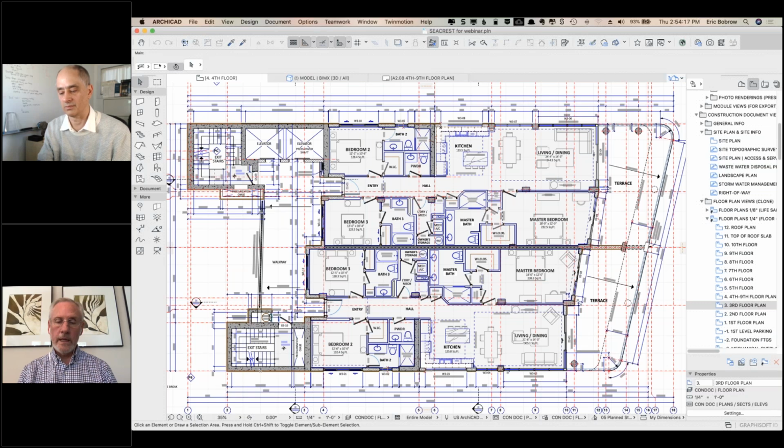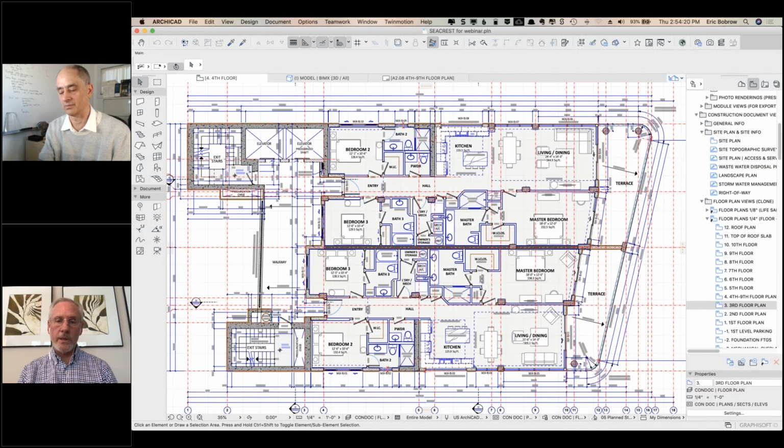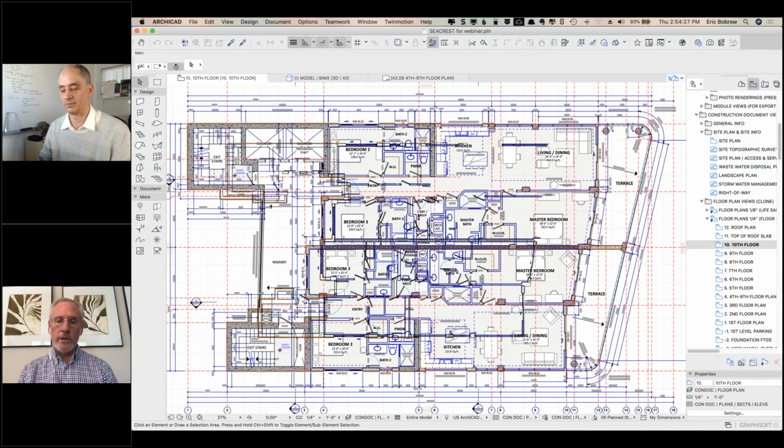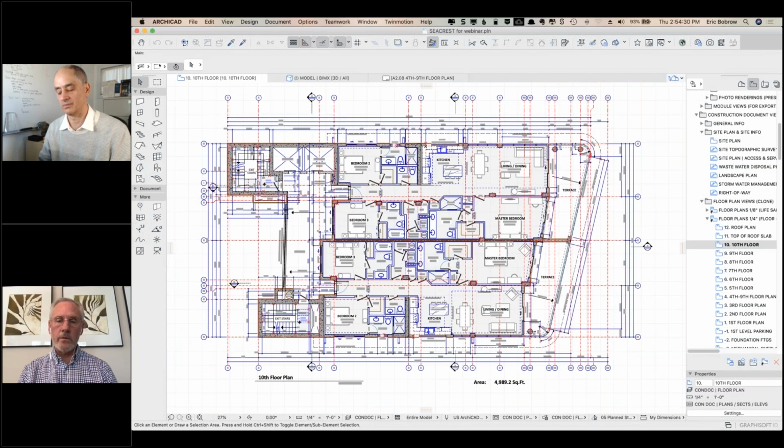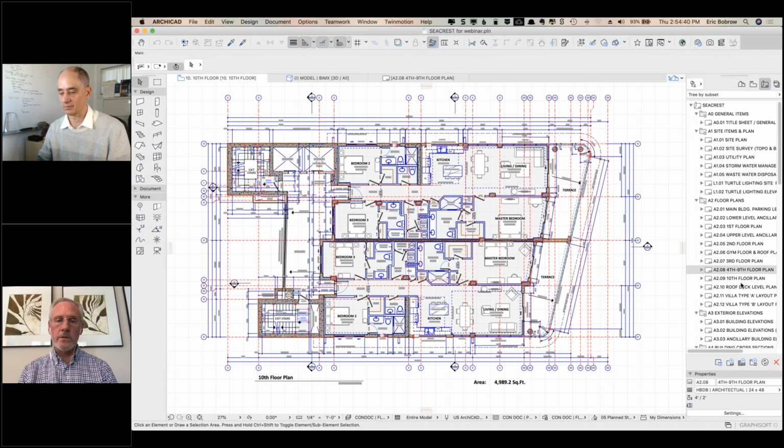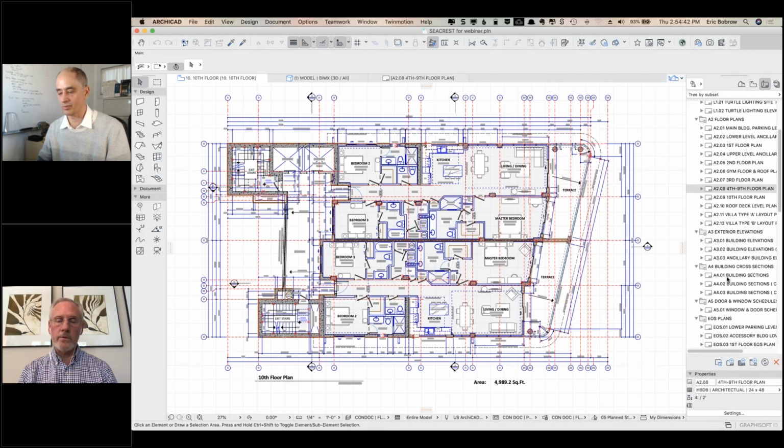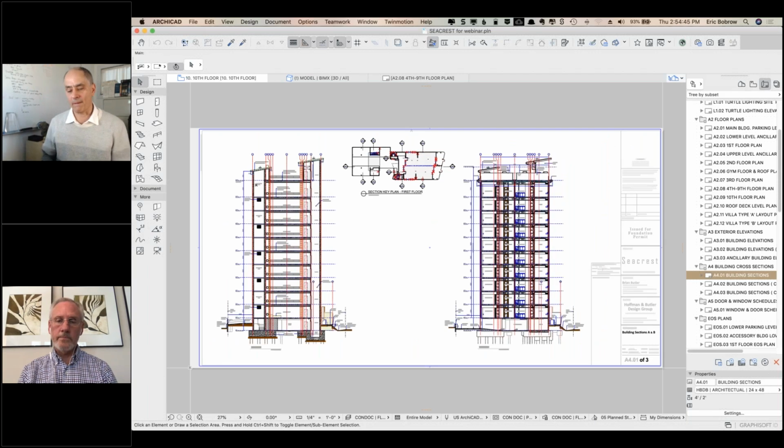So all the interior walls, steel stud walls and cabinets and furniture and all that kind of stuff is in the module. And then the 10th floor was different because I played with it and couldn't figure out how to make it work, because the 10th floor has a different story height. It's a taller story. So it didn't seem to work well because the walls are actually connected or related to the story above it, a certain set down, and the floor slabs are a different thickness than the roof slab above the 10th story. Right. So I have two modules basically.